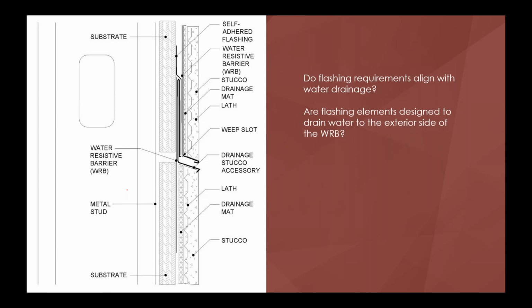So there's no big need for an expansion joint, but you don't want the water that gets in, let's say on the top floor, to have to come all the way down to the bottom floor to wick out. Just picture it, you pick up more and more water as you're going down. If I'm going to minimize the water in my system, I want to redirect that water out on every floor. So this is a great way, put this at every floor line. And what that's going to do is force that water out here, here, and out.